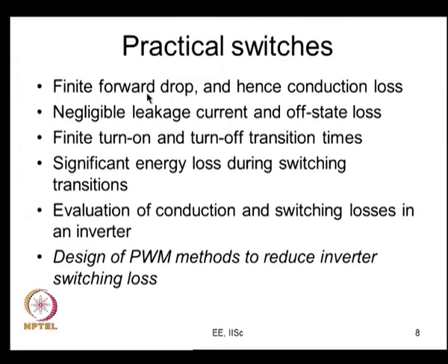What about the practical switches? They have a finite forward drop, therefore there is a certain amount of conduction loss, and there is negligible leakage current, and therefore the off state loss is also negligible, we do not have to worry about that. What we need to worry about is mainly the conduction loss during the on state and the losses during the switching transitions, because the turn on and turn off transition times are finite, and there is a significant amount of energy loss during these transitions.